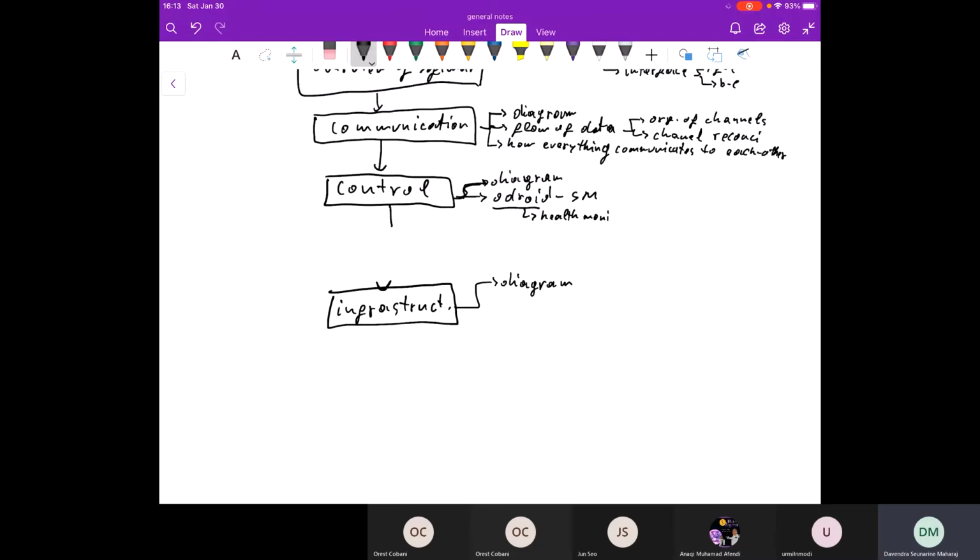For instance, if we lose comms with a critical system like the motor or the brakes, the controller should decide it's not safe to drive and go into a state like emergency. But that's the worst case. In the normal case, we just collect the data and ensure that there's comms. If there's no comms, we want to be aware of that, so we can trace back what happened.